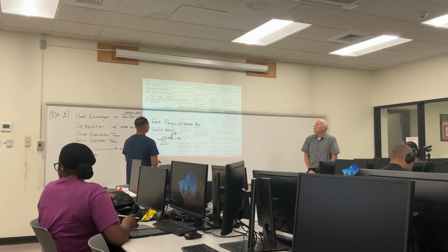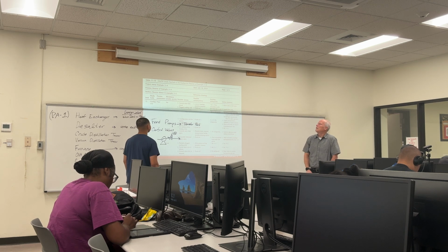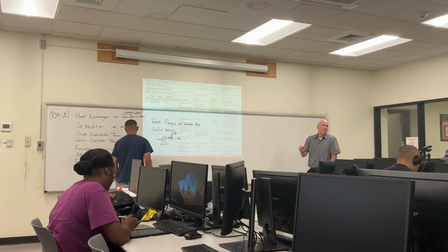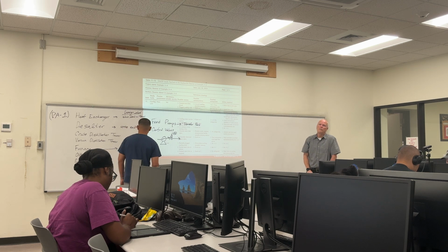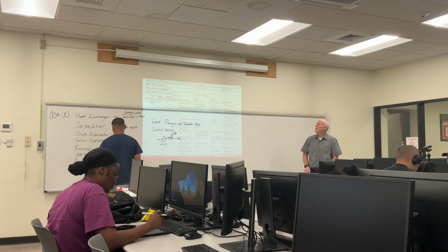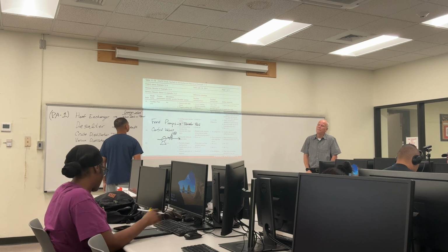So the consequence of no flow, we said, is loss of flow through a furnace: tube rupture, fire. Okay, that's the consequence of our feed pumps not doing what they're supposed to.